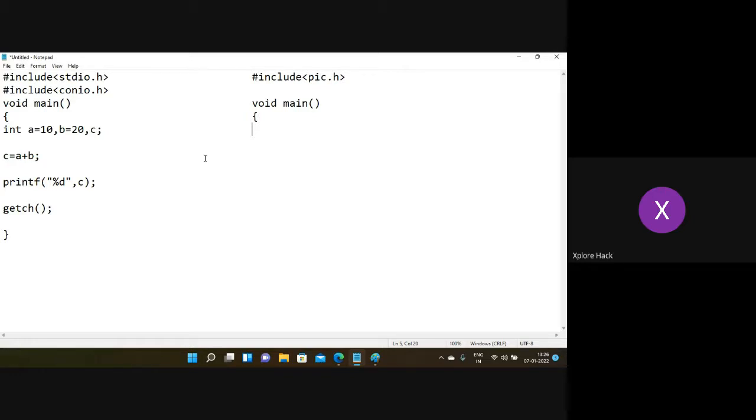So if you are converting the pins into different modes, then you have to tell the rest of the unused pins to act in a specific state. Okay. To do that, there are three different concepts that can be applied. One is that all the 8 pins can act as output, or all the 8 pins can act as input. Sometimes you can configure 4 pins as input and 4 pins as output also. So to make the port understand which pins we are going to use and which pins need to be configured as output.